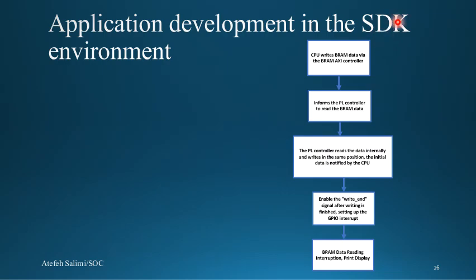If you are familiar with SDK, migrating from SDK to Vitis is not a big challenge for you. Don't worry about that. We have to run different steps here in order to complete a project. First of all, we have to create a board support package.